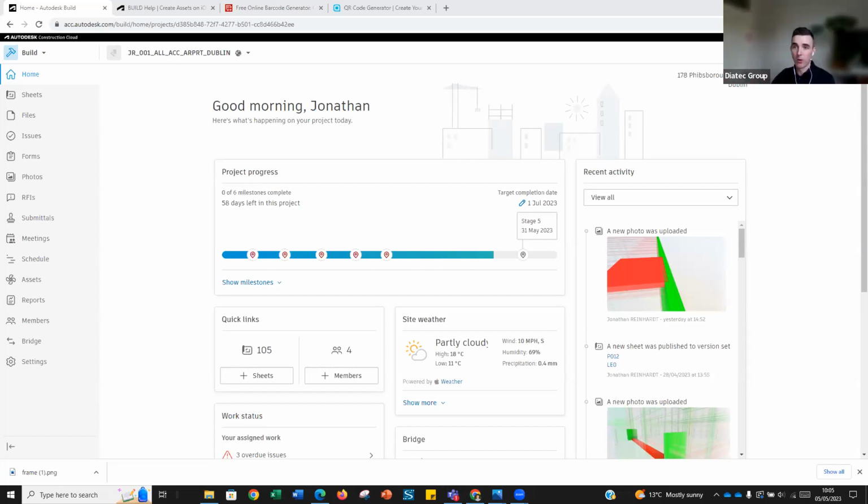So what we're looking at, as you can see, I'm logged into Autodesk Construction Cloud. You can see that in the top left-hand corner. And that's where these workflows typically are executed. There's some external integration that I'll show, things like bringing models from Revit. I will show you how to do that and maybe extract some of the parametric information as a barcode, like your IFC or your GUID. You could turn that into a barcode. So I'm going to show you some of those workflows as well.